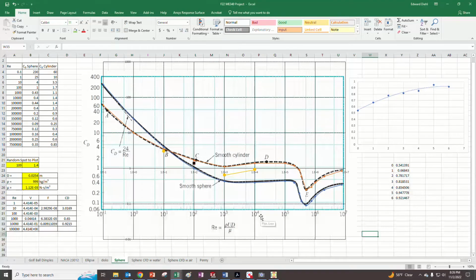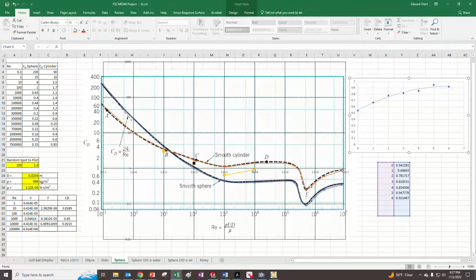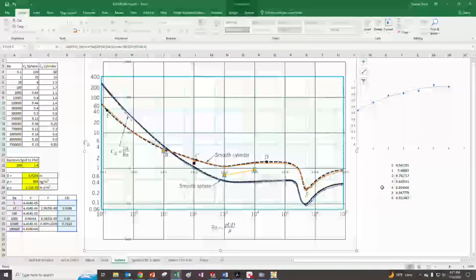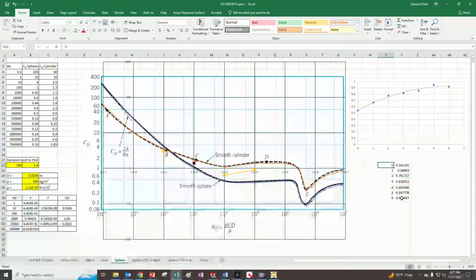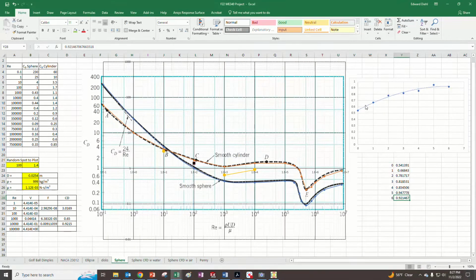And the best way to do that, okay, we're at the 21-minute mark. So right there, that's probably a pretty good start, but we want to do something else. If you notice up above, I actually have a graph up here, and for this 10,000 point, I really went to town and kept increasing this local thing, and it really bogged the machine down, but you could see that it converged eventually, and it was getting better and better as we were going along. But this is the drag force that I was getting initially, so you can see how bad this was over here.